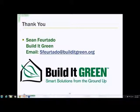So I got a question for the alternatives tab. What if I have two different types of windows? What you would typically do if you have multiple types of windows, let's say I have a slider in some situations and I have double hung windows in some situations, and the double hung window has lower performance than the sliders, you're going to be using the solar heat gain coefficient and U-factor from the lowest performing window, not the highest performing window, and they're not averaged.